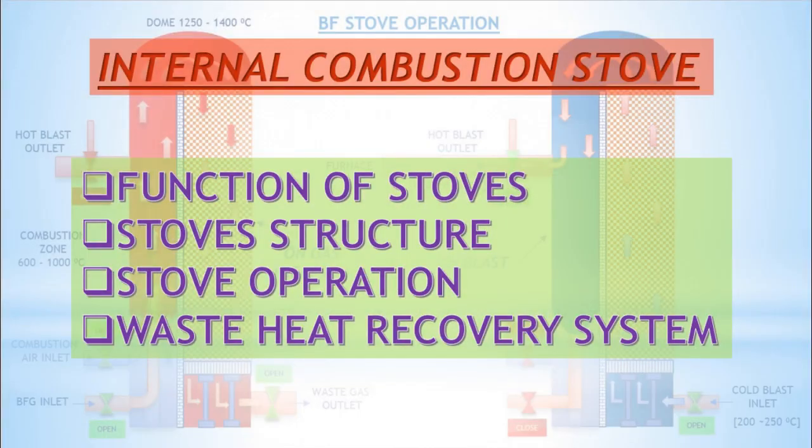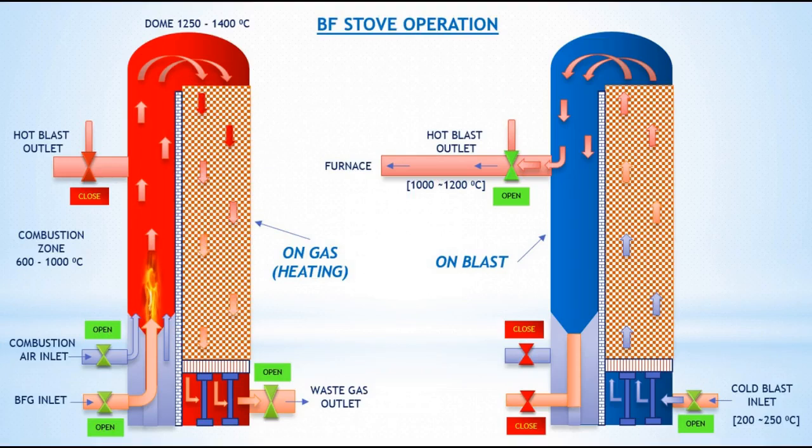Today we will discuss internal combustion stoves. A stove is basically a huge steel structure outside with refractory materials inside. Refractory brick checkers absorb heat during the heating cycle and release heat during the cooling or on-blast cycle.